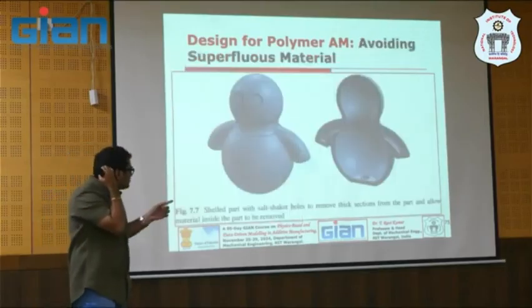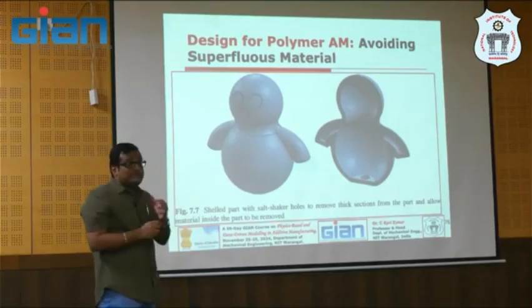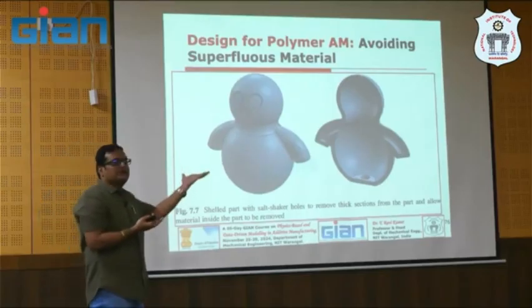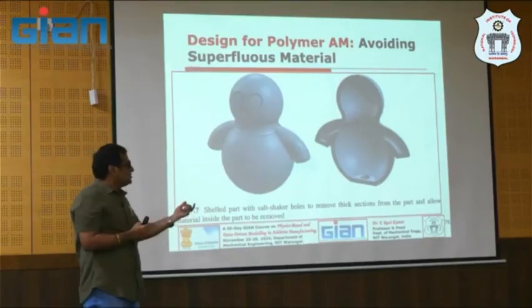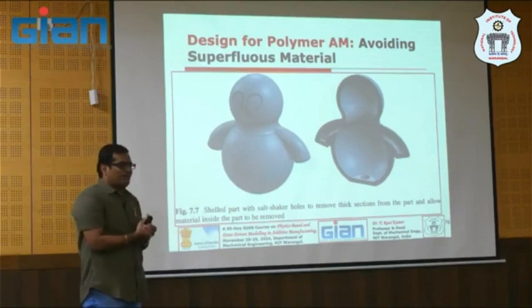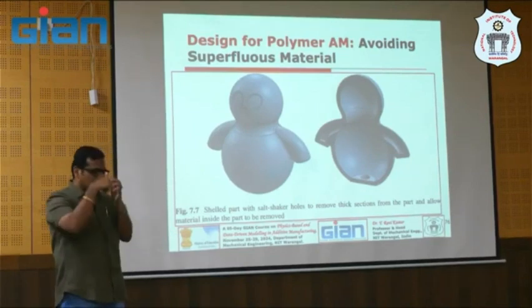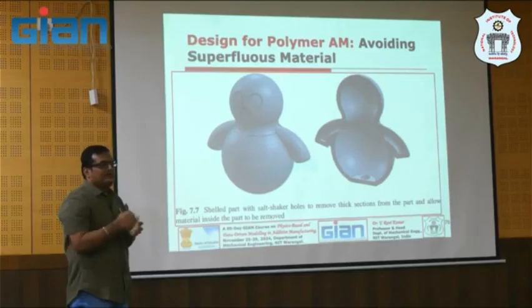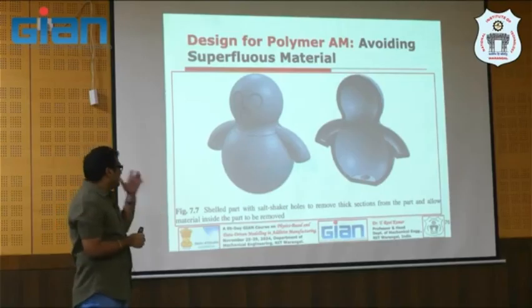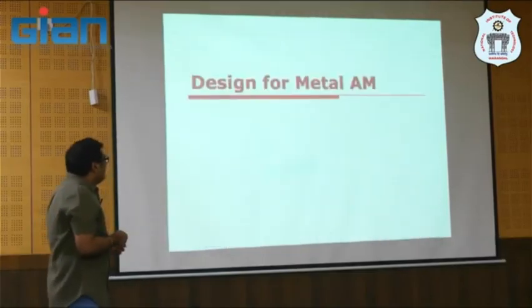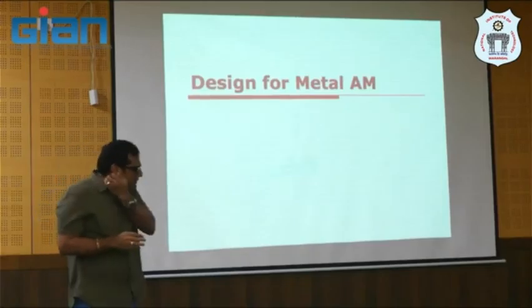And then you have salt shaker holes, especially for the vat system or powder bed system, right? If you have a hollow part made through a powder bed system, you are stuck with loose powder inside, and in a vat system you have entrapped liquid inside the hollow feature of your part. So we need to evacuate that material inside. For that also we have some guidelines to be followed. Yeah, that is about some polymer design aspects.